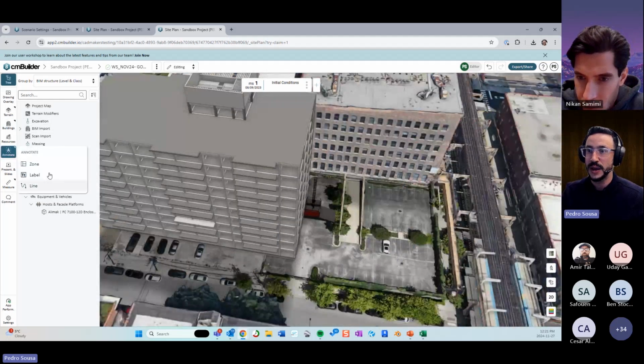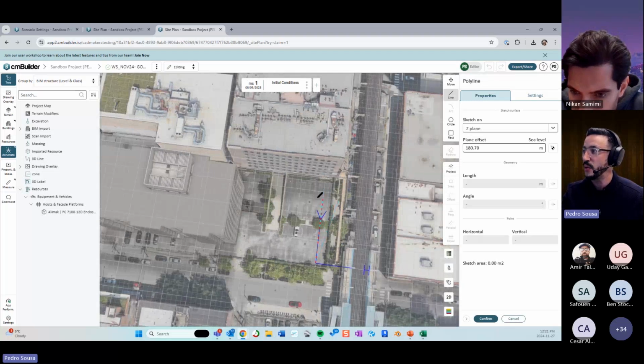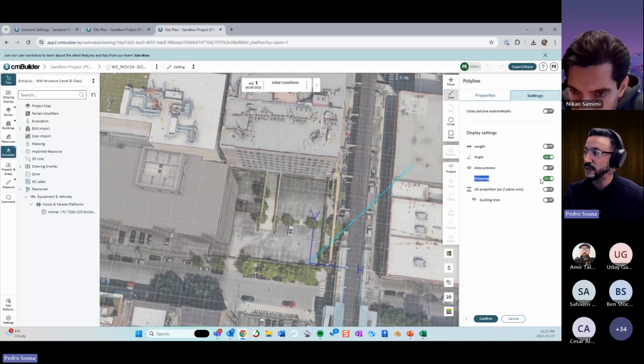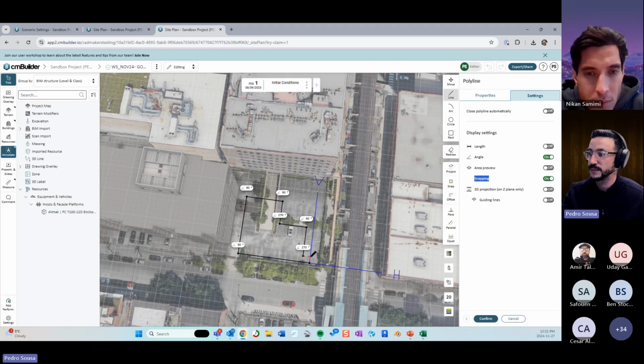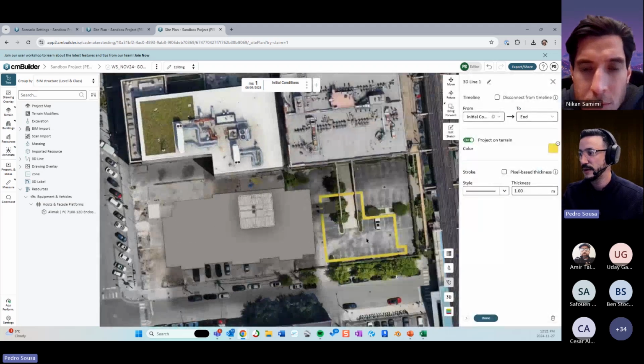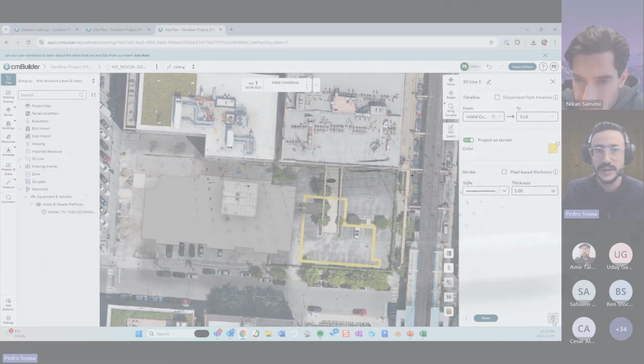So when you put in a sketch and you want to snap it, if you turn this on, this will always give you references according to the vertical and the horizontal positioning of these references. Cool. There you go. So now I have a little line over there that's all aligned with my project north.